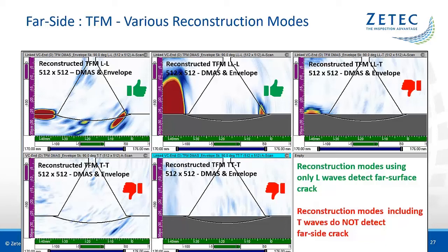This last example clearly illustrates the benefits of recording the raw FMC data. By doing so, all basic information is available during data analysis, and the advantages of each wave mode and reconstruction algorithm can be fully exploited. Even if FMC raw data saving on a complete weld is still a laborious and time-consuming process, taking FMC snapshots or short scans in flawed or suspicious regions can be a valuable compromise.